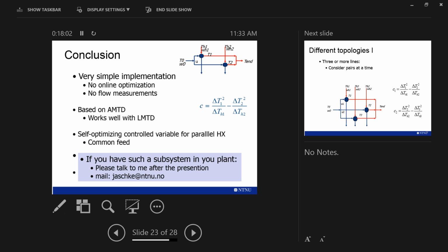Did you consider the minimum temperature difference approach using the heat transfer coefficient? Sorry, can you reformulate your question a bit? I'm not quite sure what you mean. In practice, we have to consider minimum temperature difference for calculating heat exchanger efficiency. Okay. So I think you typically do that when you design a heat exchanger. And when you design the heat exchanger, a simple way to balance cost and efficiency is to use this minimum temperature difference.